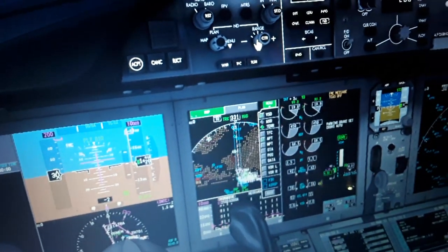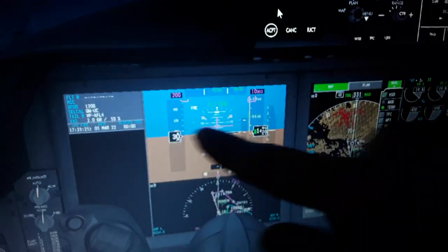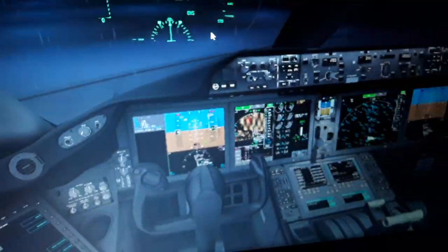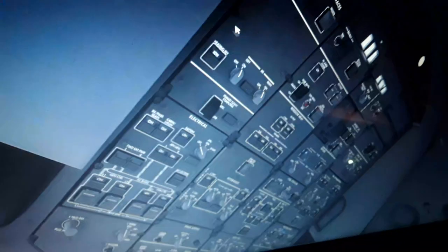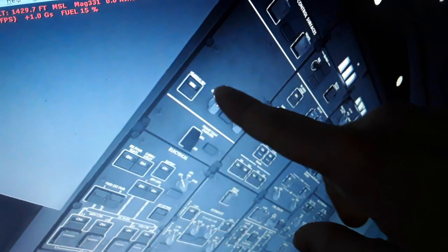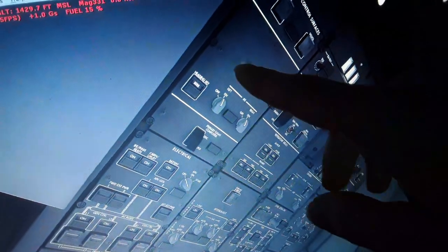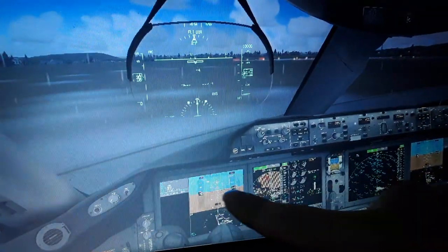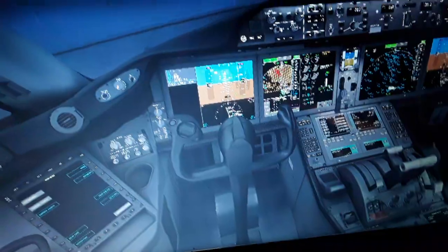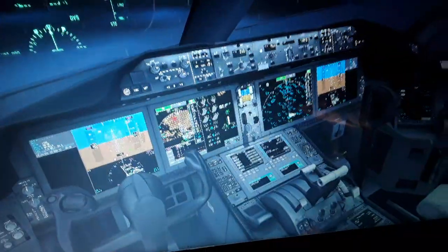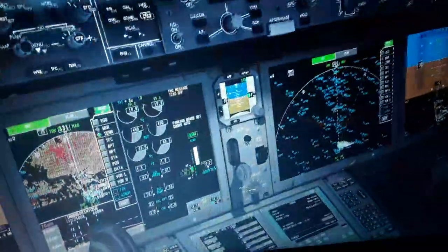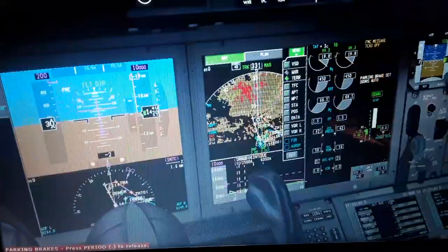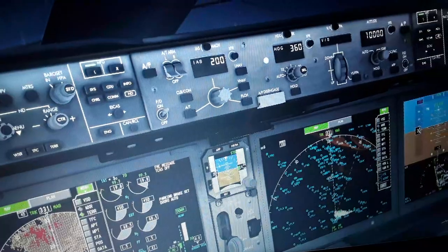So we'll look closer. You can see the airspeed again, altitude, barometric altitude. So we have the air data computer over here, controls, monitors and displays, pitot static, pitot barometric, laser gyroscopes, GPS receivers. So the dynamic airspeed and barometric altitude are set from the air data computer. Also the attitude, laser gyroscopes, other things, angle of attack as we fly, temperatures, pressure.